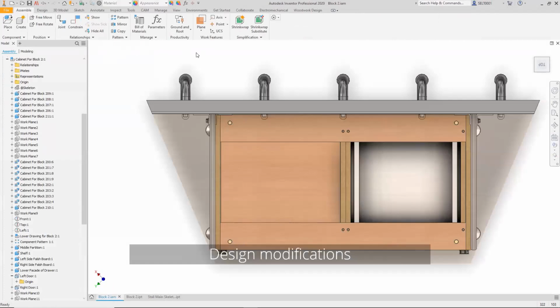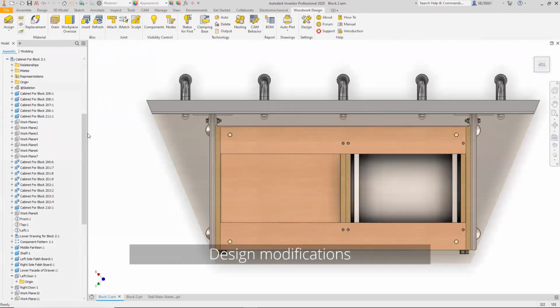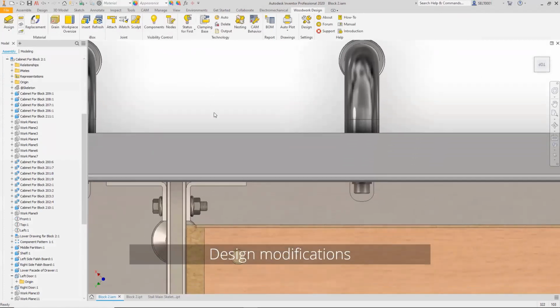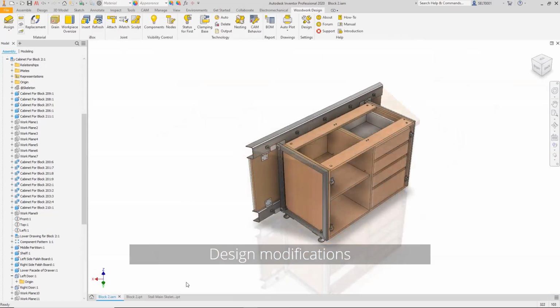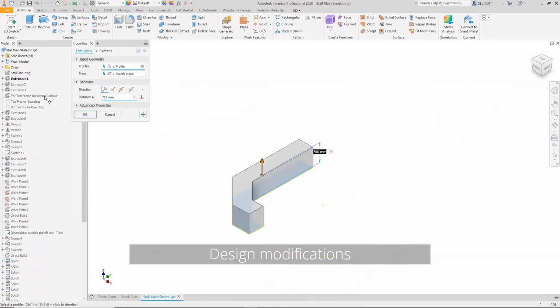So we change the skeleton concept, then we refresh the changes. And that's it. So now there are no intersections. We can visually check if there is a clear area, if there is the needed clearance between the items. And if you see that there is spacing, there's the support on the bottom, which doesn't make any sense in this case. Seeing on the top portion, there is no intersection anymore. We can see what will happen.